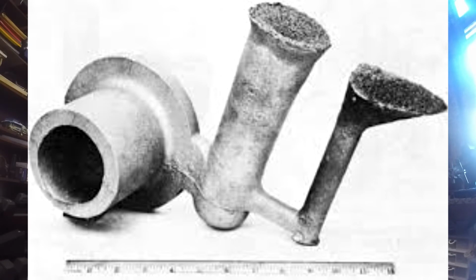In addition, they don't have a place for that dross to go other than directly into the mold cavity. Unless it got shifted up, no, it wouldn't have, because the riser is the last thing you get fed. So that dross went into the mold cavity. And somewhere in there, that's obviously going to be something that's going to have pressure on the inside. I'd be worried about the integrity of that pressurized vessel.